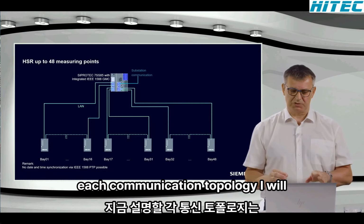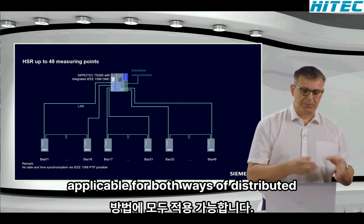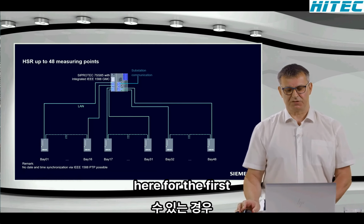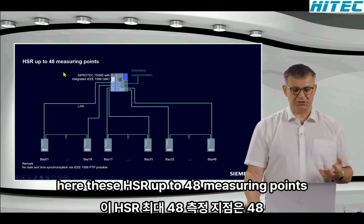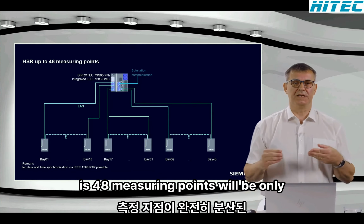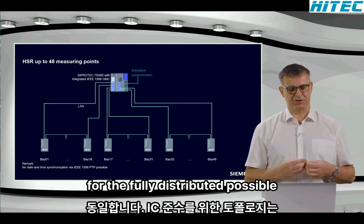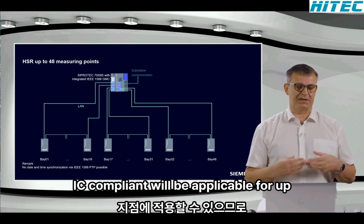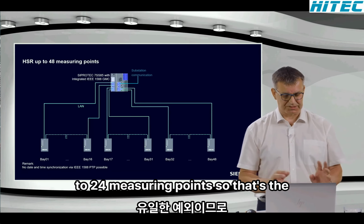Each communication topology I will explain now is applicable for both ways of distributed busbar protection. Of course, the first one here, HSR up to 48 measuring points, will be only possible for the fully distributed busbar protection, but the same topology for the IEC compliant will be applicable for up to 24 measuring points. So that's the only exception.